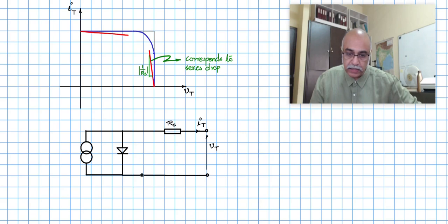If there was a shunt resistance, part of the photon current from the current source will get diverted into a shunt resistance, and that is the current drop that you see here, which does not reach the terminal current. So this will have a slope again, and that is 1 by R shunt, because current is in the vertical and the horizontal is the voltage axis. It is 1 by R shunt and 1 by RS.